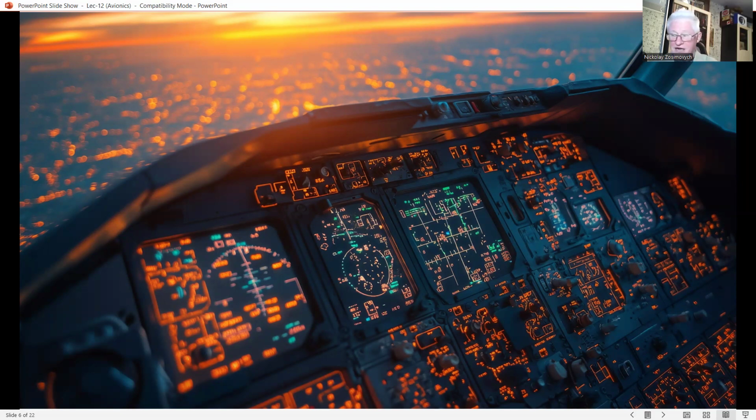Positioning data include GPS, VOR, DME, TACAN, terrain reference navigation system, radar, visual fixes like use of a helmet-mounted sight, and astro or stellar navigation, which uses an automatic star tracker. Velocity data contains only two components, Doppler radar and GPS. Altitude data contains two components, barometric altitude from the air data computer and radio altimeter.